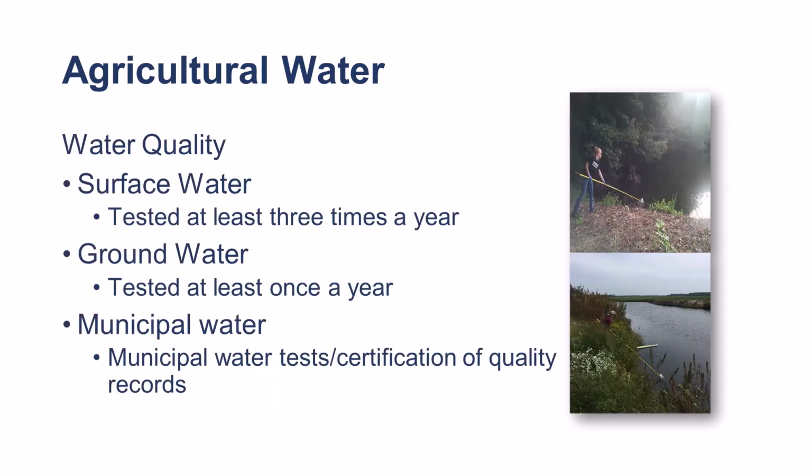All surface water and groundwater sources should be sampled and analyzed to determine the total coliforms and generic E. coli in your water. During the active growing season, all surface water sources should be tested. Refer to the fact sheet of this module for the number of tests needed for your water source. Groundwater should be tested at least once during the growing season.